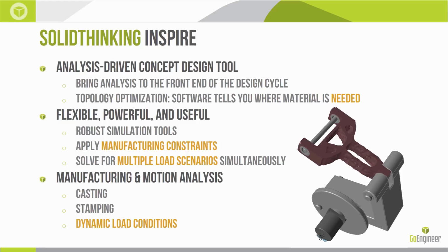Topology optimization has historically delivered very organic shapes, things that were kind of unmanufacturable. That's no longer the case now with 3D printing, but only a very, very small sector of the market is actually 3D printing end-use parts. Most people are still machining parts, casting parts, molding parts, and this is where Inspire differentiates itself. We can constrain the results to accommodate those methods of manufacturing.